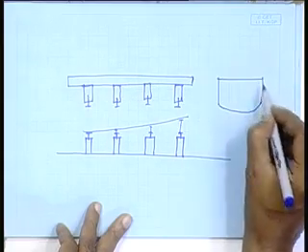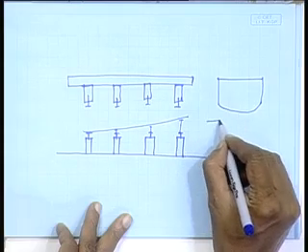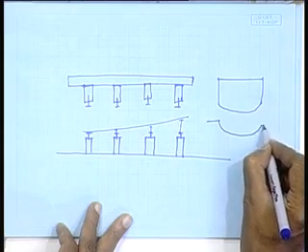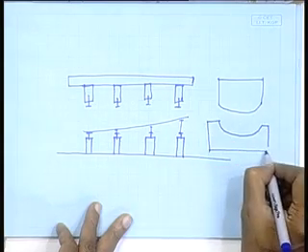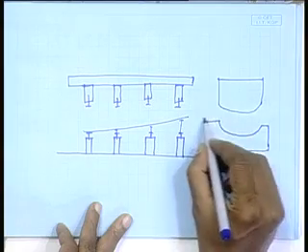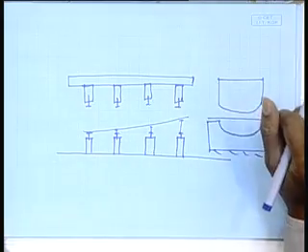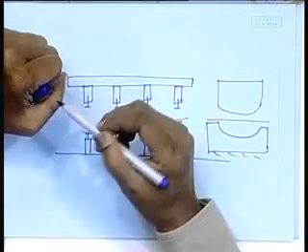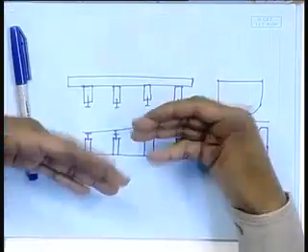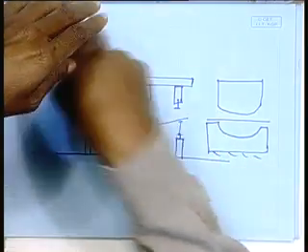This is my fixed thing and this was my female die, fixed shape. So the plate was kept here and you give a punch, you get that shape. But here this shape I am generating. So for all different shapes, it can be easily generated and bent. It can have the necessary power. So that is what is the universal die or universal press.